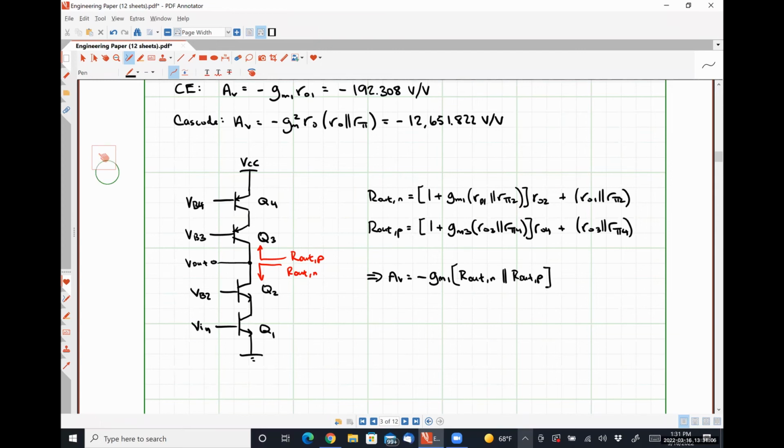Pretty much, yeah. So you would have the output resistance, this extremely large output resistance in parallel with just R0, which is going to look like something a little bit smaller than R0. So it's actually going to behave slightly worse than the common emitter stage by itself. So it's a real bad idea.